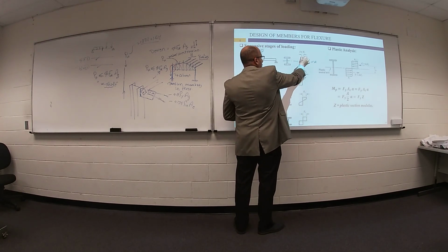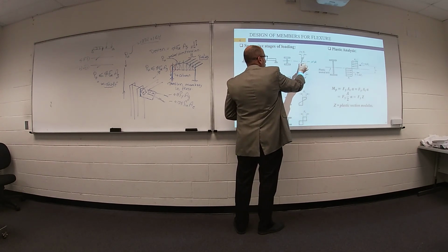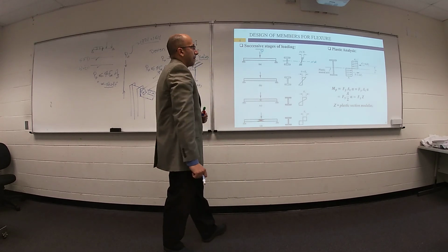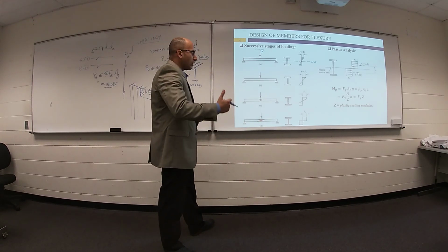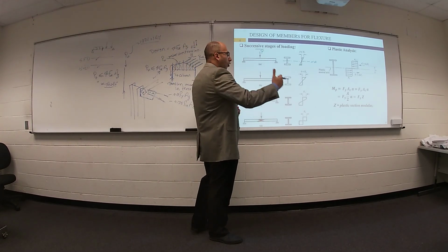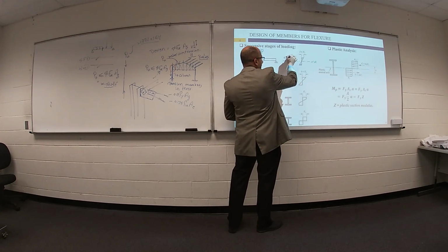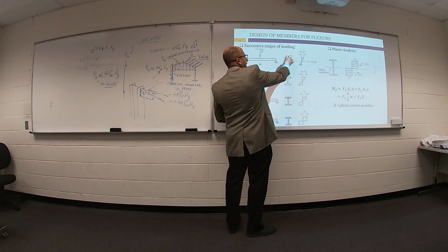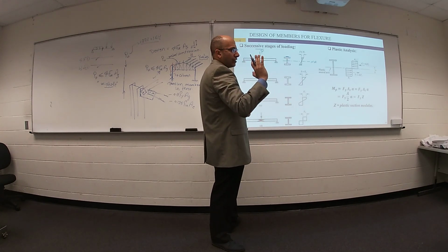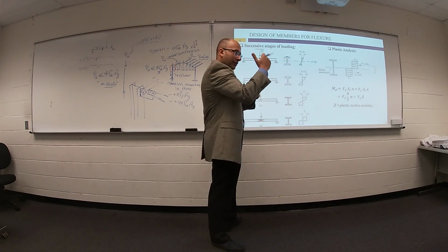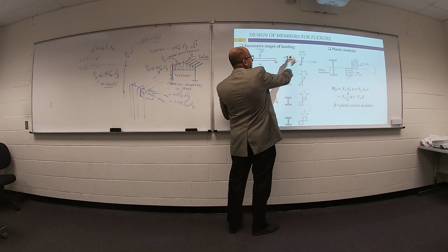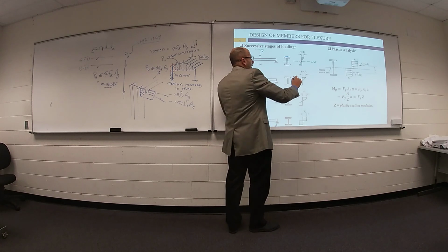One side we have compression, the other side we have tension. If your load increases more and more, your stress at this location, anybody remember the name of this location? Extreme fibers. Extreme fibers means the top point and the lowest point.